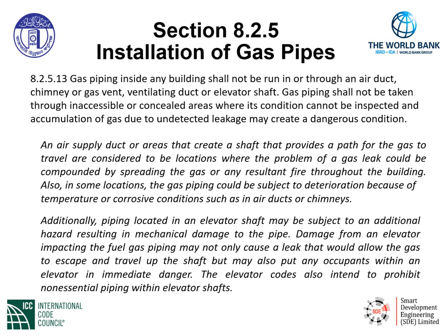maybe an area that creates a shaft that provides a path for the gas to travel, are considered to be locations where the problem of a gas leak could be compounded by spreading the gas or any resulting fire through the building. We need to understand exactly where this piping is to be installed. Also, in some locations, the gas piping could be subject to deterioration because of temperature or corrosive conditions, such as in air ducts or chimneys.